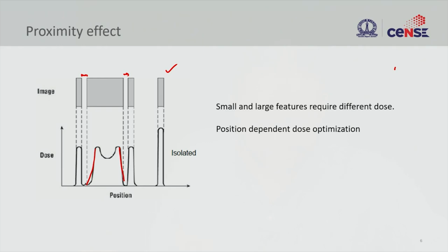The reason for that is the dose from these two will affect each other, and that will create undesirable critical dimension variation.